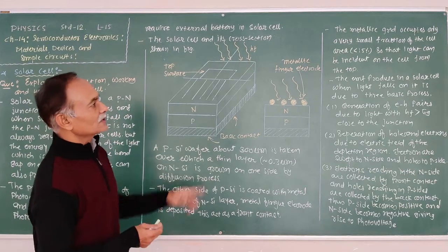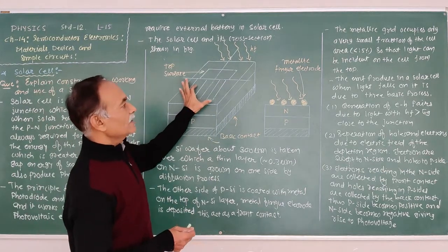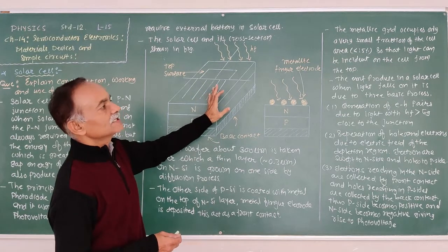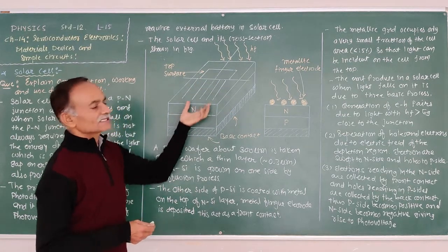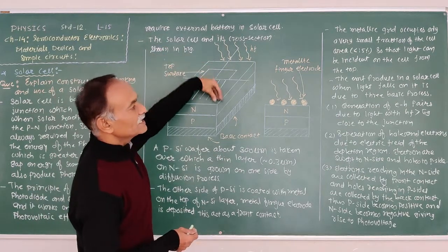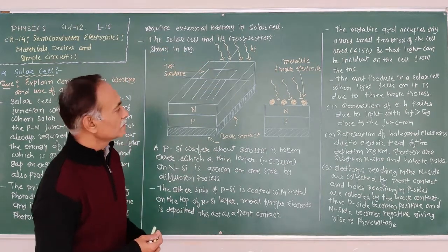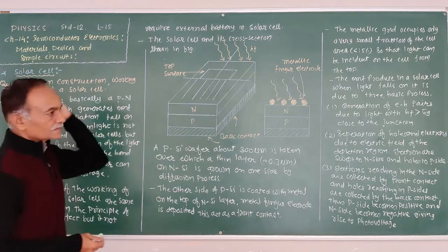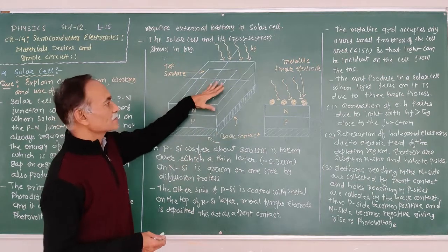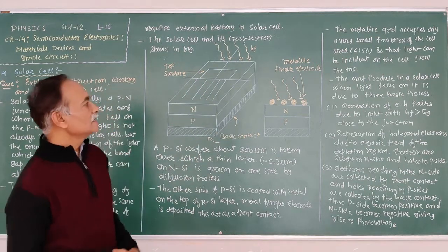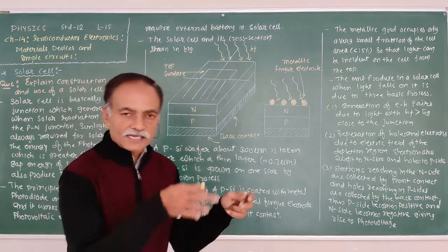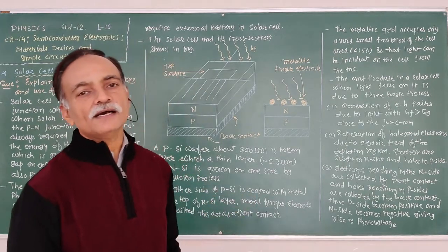So as a result, what happened? A very small fraction of the cell area, less than 15%, is occupied by this metallic contact, so that light can be incident on the cell from the top. Due to that, this type of finger metallic electrode is placed on the top of the solar cell. So within this gap, the light can enter the N silicon and reach the PN junction.